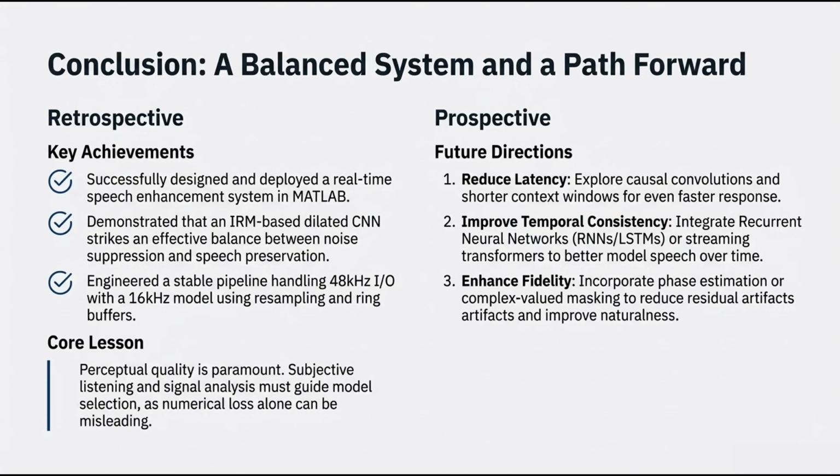To wrap up, we successfully built a real-time speech enhancement system in MATLAB. The IRM-based dilated CNN offered a strong balance between noise reduction and natural speech. The end-to-end pipeline handled 48 kHz input-output, 16 kHz model processing, buffering, and post-processing for stable streaming.